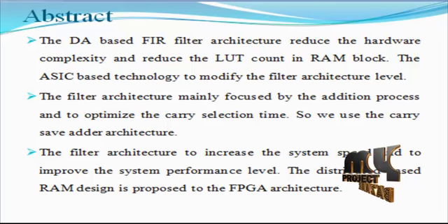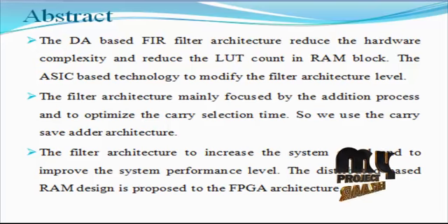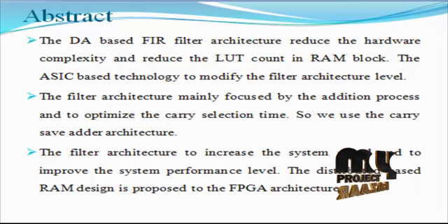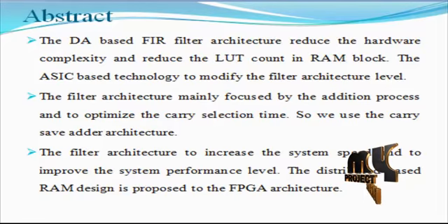Bit slices have different weightage. The proposed design achieves nearly 68 and 58% less area delay product and 78 and 99% less energy per sample than DA based systolic structures and the carry save adder technique. The carry save adder technique is used for the ASIC realization of DA based reconfigurable FIR digital filter architecture.